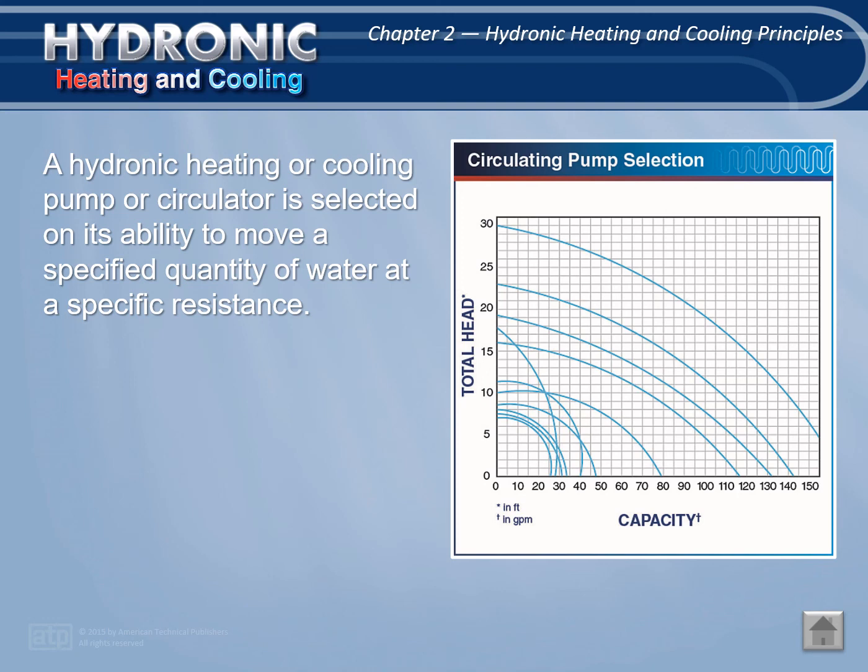Water flow rate needs in hydronic systems are based on the temperature difference of the water at 2 points in the system and the amount of heat transferred during the change of temperature. Water flow velocity is the speed at which water moves through the piping section, typically expressed in feet per second. Water flow velocity in hydronic systems is based on the water flow rate between 2 points in the system and the size of piping.